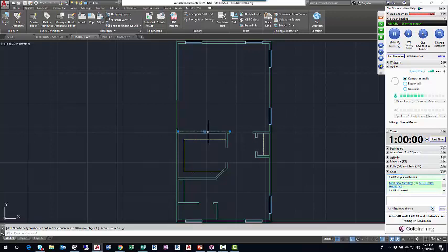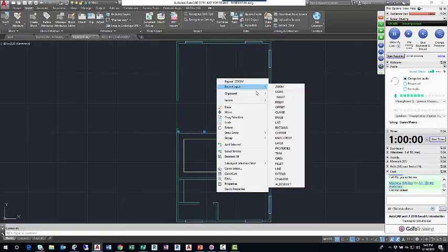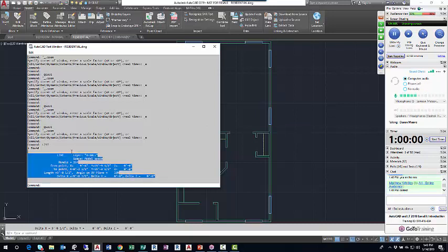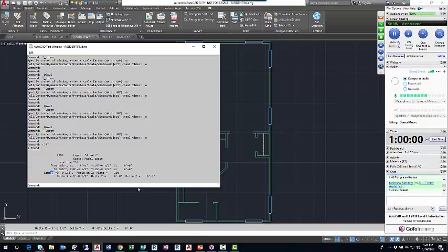you saw with the list command, I'm going to right click and go to recent input, list. With the list command, AutoCAD tracks everything about everything that it can in the drawing window. AutoCAD calls that line that I just selected 26F. Everything in AutoCAD has what's called a handle. AutoCAD says okay, 26F is a line on the layer A wall, it lives at these coordinates, it's at this angle, it's that length. There's almost like an Excel spreadsheet in the back office of AutoCAD. Everything has an entry in what's called a handle table.